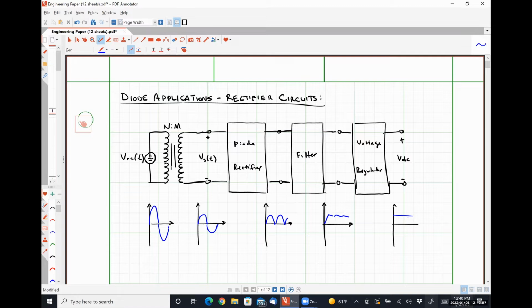So we observed, I believe, that we could change our supply voltage by as much as 1 volt and only saw a few millivolts of change in our DC output, right? So we're getting a pretty good DC output by the time we hit our voltage regulator.